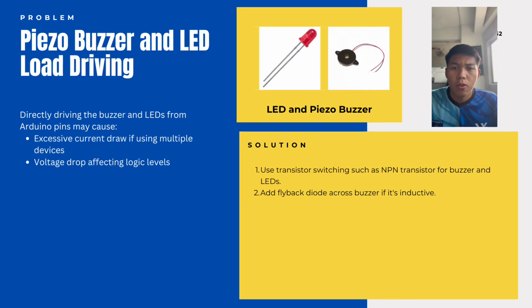So next, I want to talk about our last problem, which is piezo buzzer and LED load driving. The problem is that directly driving the buzzer and LEDs from Arduino pins may cause excessive current draw if using multiple devices, and lastly, voltage drop affecting the logic level.